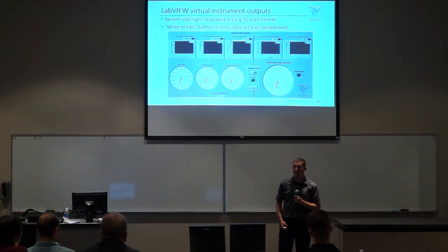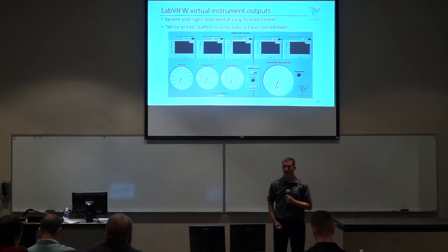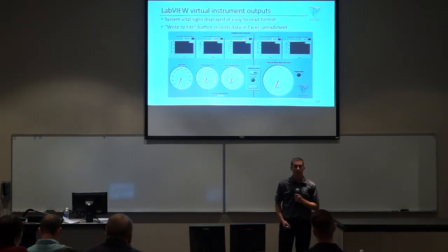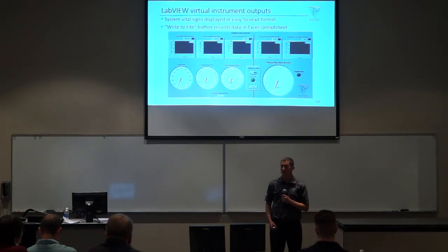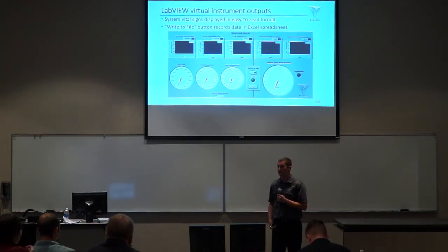Across the bottom from left to right, there's a gauge for the engine RPM, the afterburner exit velocity. Down below, there's a small indicator for the afterburner exit air density. Then there's a gauge for the mass flow rate. On the far right, the large gauge is the Mach number of the exhaust flow with a supersonic indicator to the right that would light up red if our measurements indicated that we had supersonic exhaust velocities.